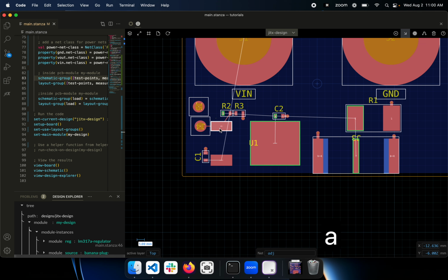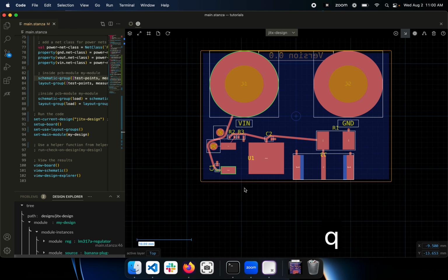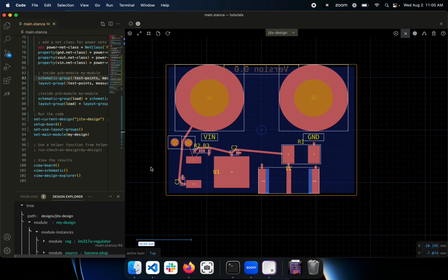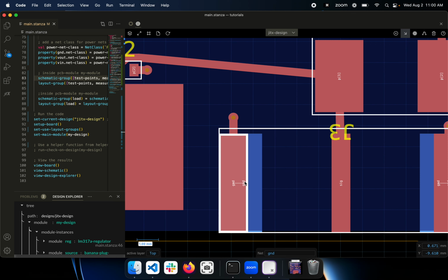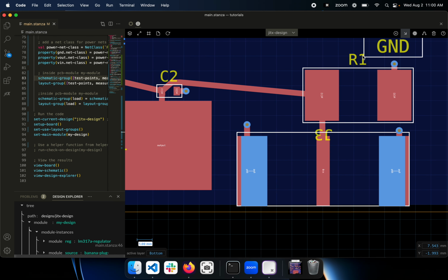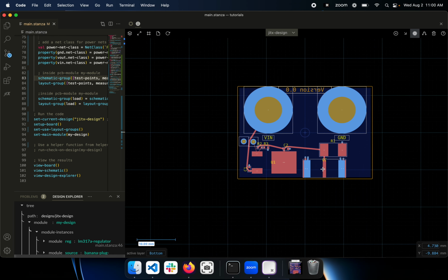Here is that's just V out. Can route that. That's fine for a test board and close enough for government work. And finally, I can just select again the input node, hit route, and it's okay. Let's say maybe I'll move that there, move this here. Yeah, okay. Not amazing, but fully routed here. And we got some rat's nest evolving on the bottom, so I'm going to shift to the bottom, select via mode, and just drag out some vias from the ground pads on the bottom for our BNC connector. And that's it, fully routed.